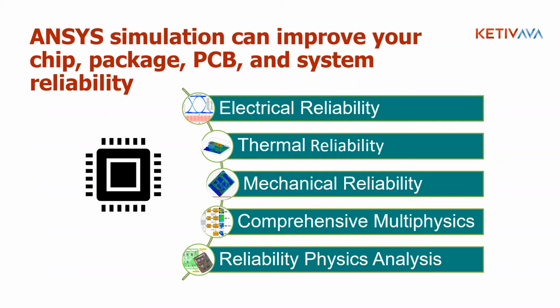And then finally, all of these reliability tests that one might do in terms of electrical, thermal, and mechanical reliability can all get fed into a larger or wider analysis of lifetime of particular piece parts, and then taking the lifetime curves of a number of piece parts, whether that's part of a PCB, and looking at the entire PCB board lifetime, or whether it's a number of components of, say, a vehicle or other product, and pulling all the lifetime information for each of the components and getting the full lifetime of the vehicle.